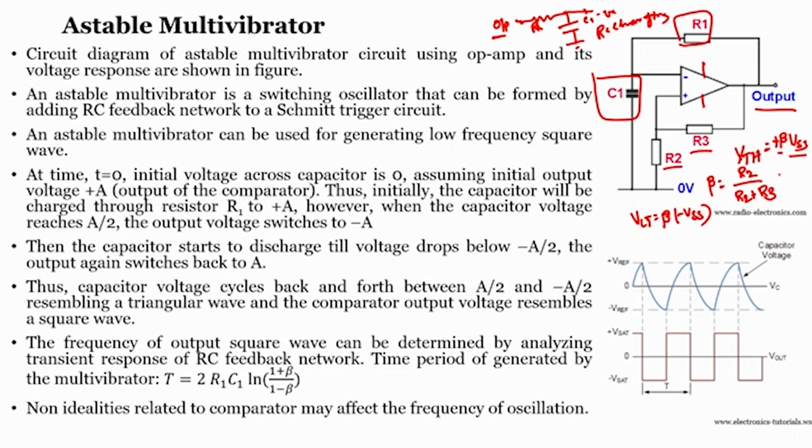And again, when the output is in the minus VCC state, whatever value is stored in your capacitor will discharge to the minus VCC state, which is a negative charging of your capacitor. So the capacitor will always try to charge up to plus VCC, and discharges from plus VCC towards minus VCC when the input of the RC filter is at minus VCC.